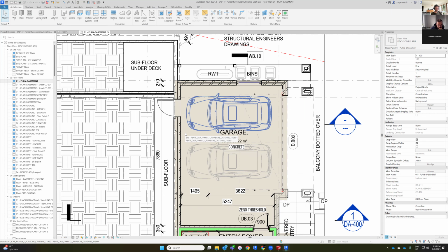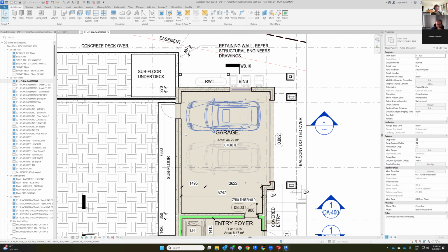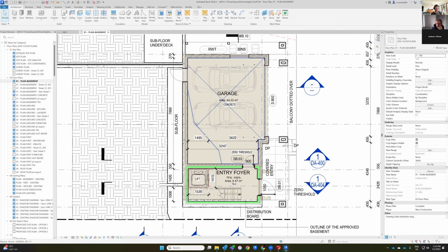Yeah, fine. And does that other thing relate to any of the building envelope walls? It's underneath. So all the building envelope is the 140 style, is that correct? Yeah. Good. And then in this section behind that wall, previously I had it backfilled against this wall. But just thinking about it, in terms of longevity of your building, keeping moisture away from there would be better to over excavate a bit to be able to keep that water off that wall.